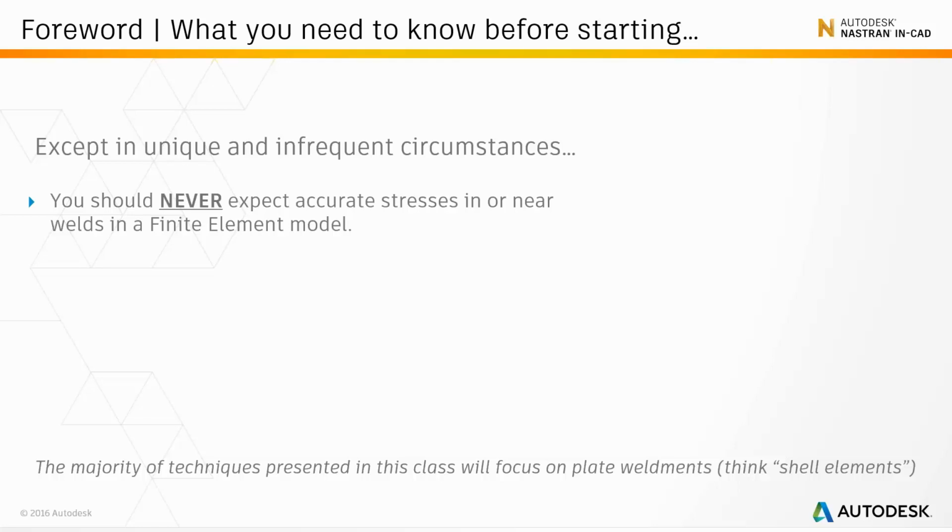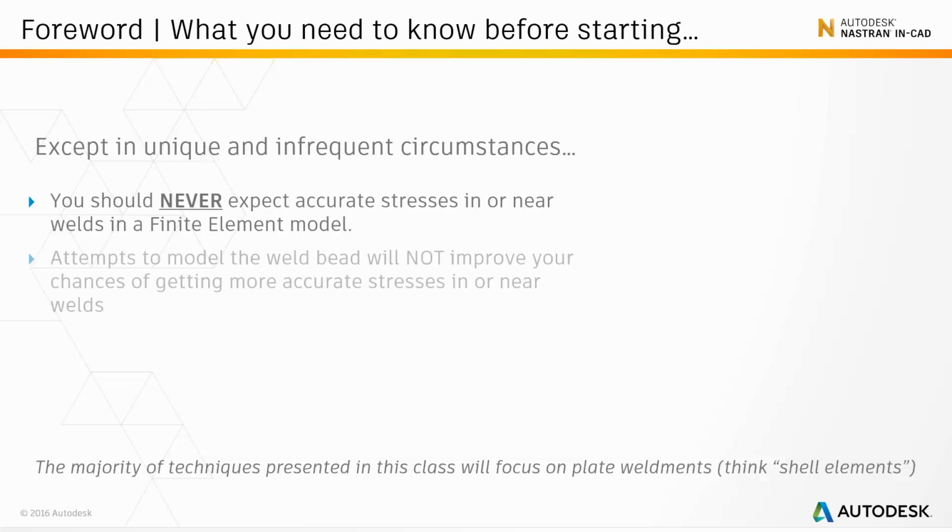So stresses are definitely an approximation inside of your FEA packages when you're looking at the welds themselves. Secondly, just because you have better CAD doesn't necessarily mean you're going to get a better result. So what do we mean by this? Just because you're going to try and reflect the weld bead in more detail doesn't necessarily mean you're going to get more accurate results.